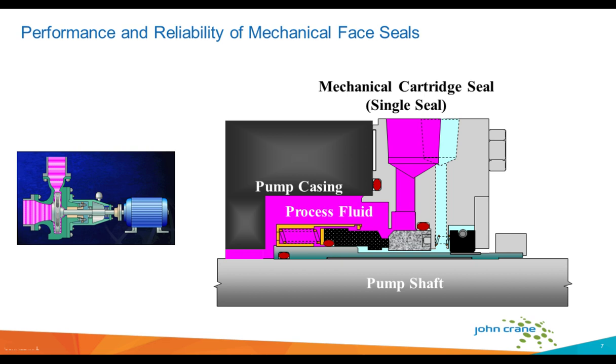First of all, let's look at the mechanical seal and understand the mechanical seal before we can look at the reliability of these mechanical seals. The mechanical seal consists of a number of components. When the seal is actually static, there's normally no leakage. You can see the fluid in the pink side. The fluid is normally on the outside diameter in the mechanical seal, or if we call it the pressure side of the mechanical seal. And the atmospheric side is on the other side.